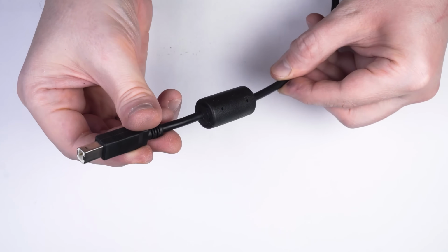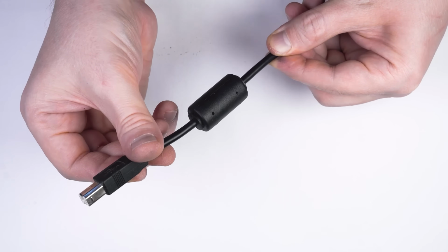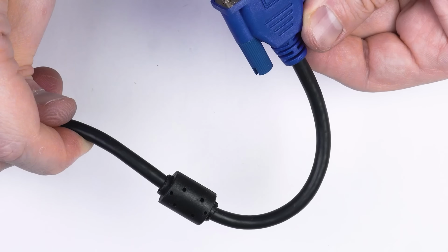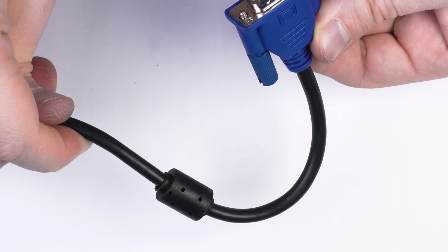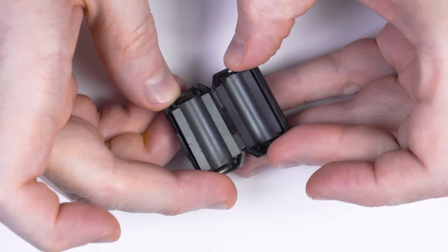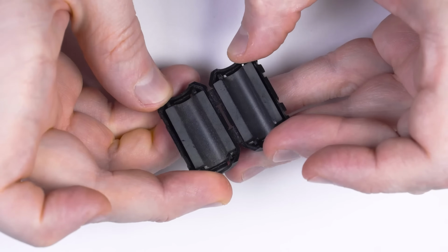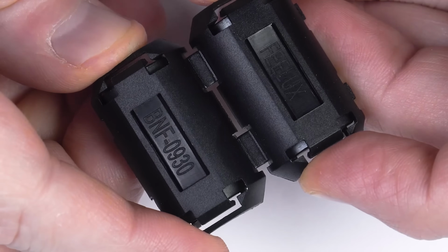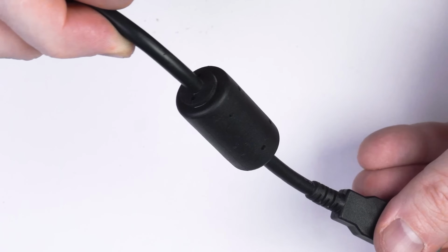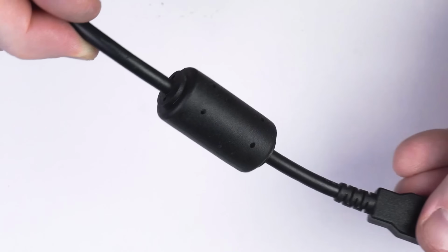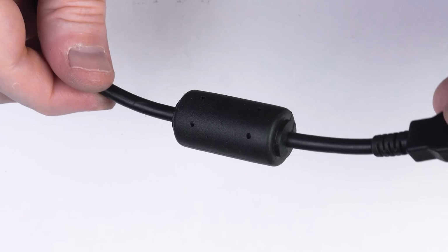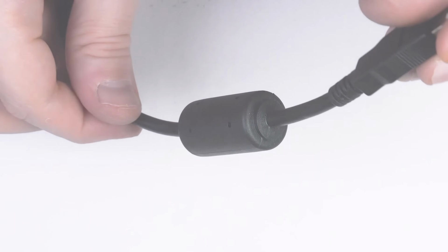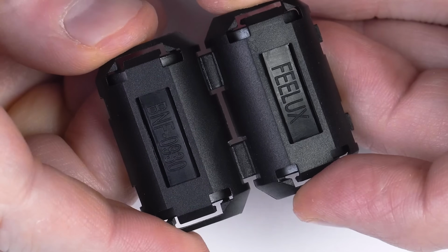And I would like to say a few words about the ferrite cores, also called ferrite beads, which can be seen on laptop power supplies, USB, and some other computer cables. Contrary to popular belief, they do not serve the purpose of protecting the device from external interference. It's actually the opposite: to limit and clean common mode noise generated from either a signal line or the power cable itself. The cable, due to its length, plays the role of an antenna, which can emit radio waves when your laptop or USB device operates. So, the ferrite toroid is needed to limit its electromagnetic interference.